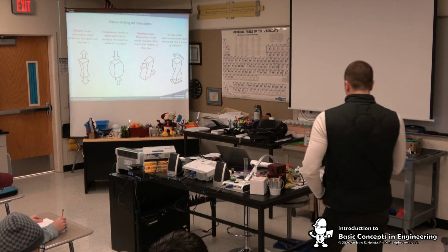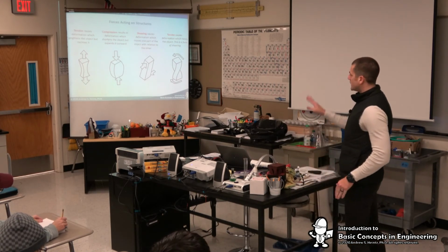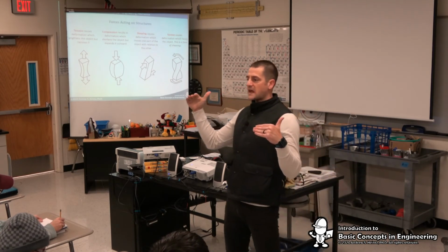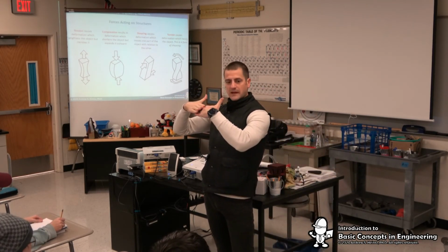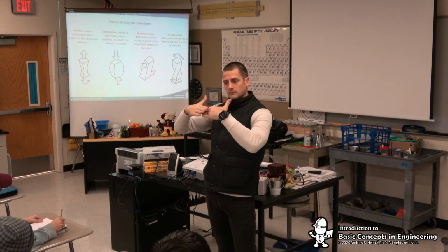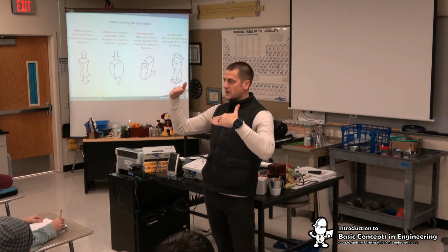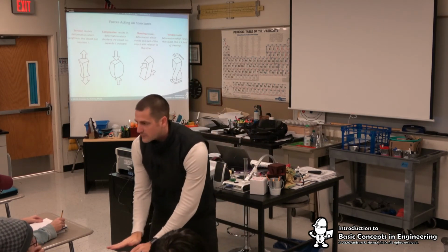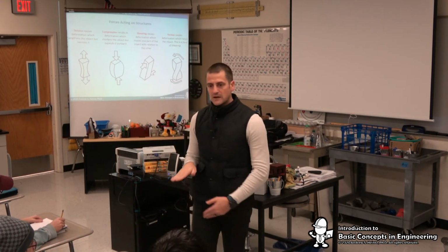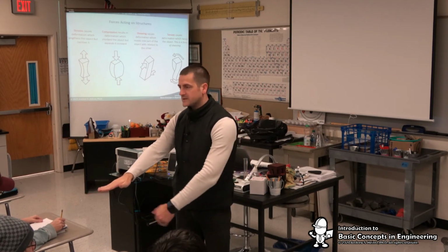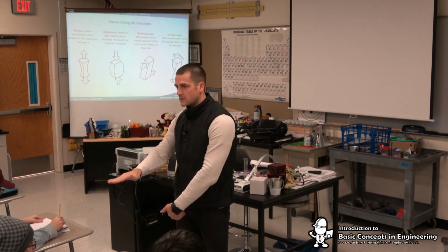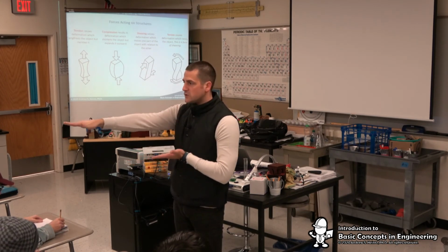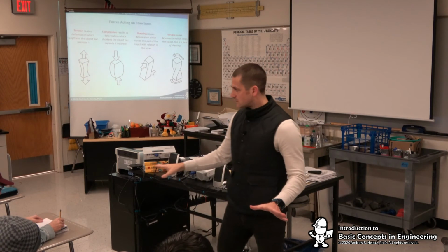We also then have, and these ones are a little harder to understand, shearing. Shearing is if I have forces acting on it in different directions, something like this. Does that make sense? It doesn't have to be 2 forces in the same direction. It could be just moving my hand across the table. I'm applying a force in one direction. In order for that not to move, there has to be an equal and opposite force in the other direction. So what you're basically seeing are the layers of molecules within that being dragged apart. Does that make sense, everyone?